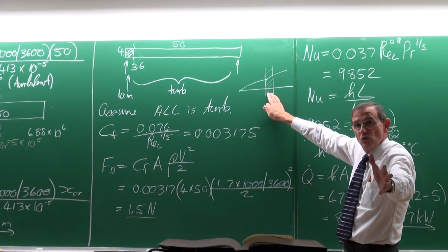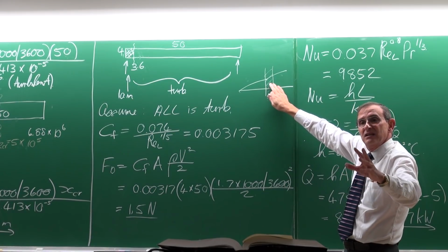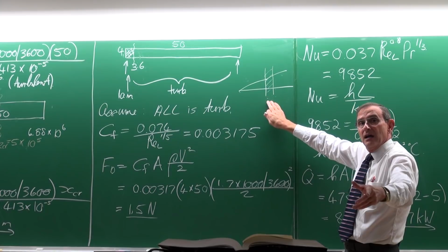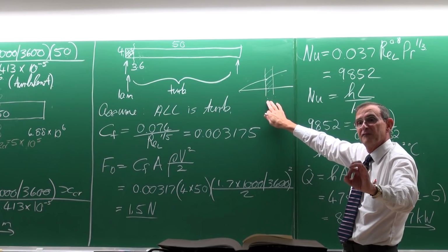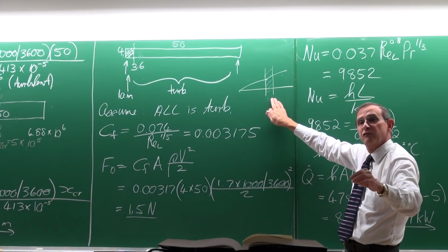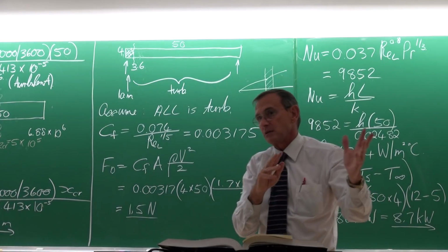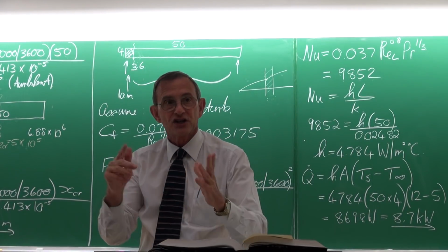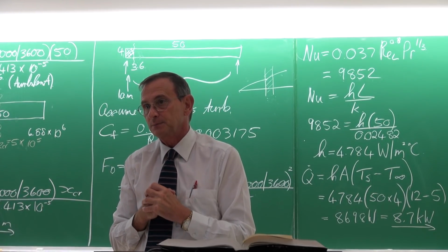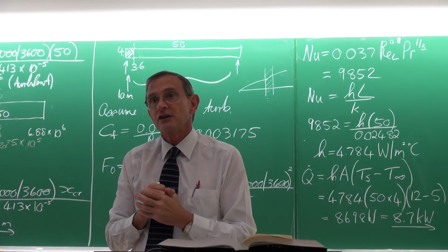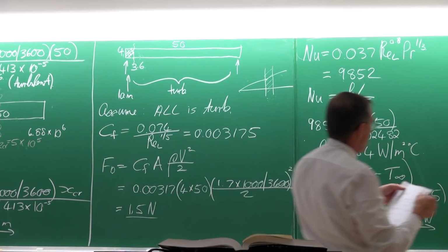There's actually no work yet for a flat plate in terms of determining really the transition characteristics. However, we have done a lot of work for smooth tubes. So if you want to have the transition characteristics for smooth tubes and or spiraled fin tubes, that has been done and that has been published, and you can actually go and determine that from the correlations which are available. Okay. Any other questions? Right, let's do the third example.